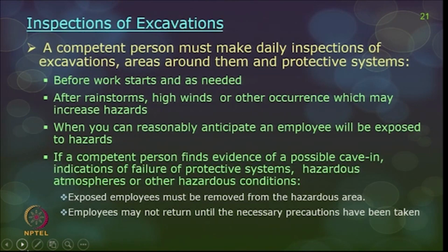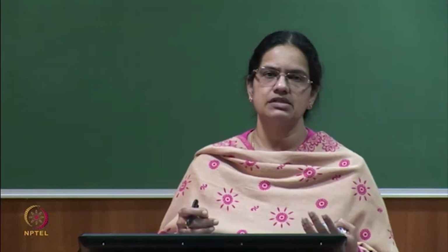Okay. Examples for all these dewatering techniques, for temporary and permanent ones. For temporary, you can easily think of pumps and so on. For permanent measures, you can think of, what is it called, diaphragm walls, or maybe well point systems. Okay, a well point system is very good for temporary means of removing water from the construction site.